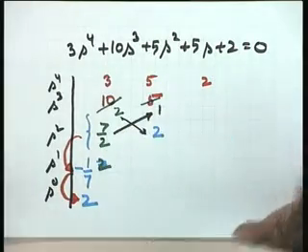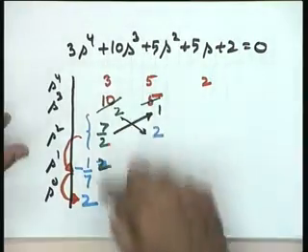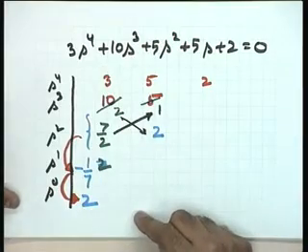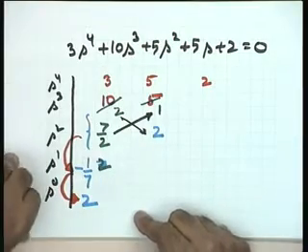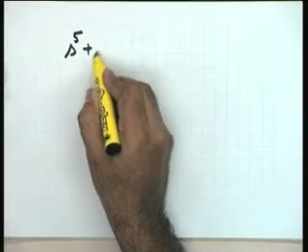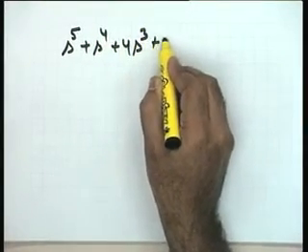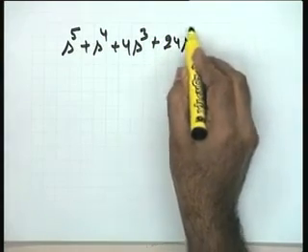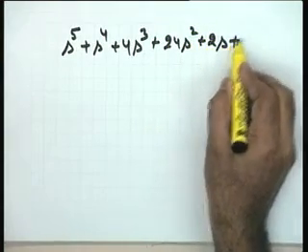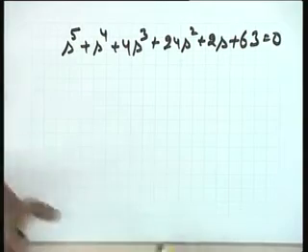There are definitely no roots on the imaginary axis if the Routh array formulation is like this. Now, let me go to a situation. Naturally, such a situation is bound to exist because the roots can be there on the j omega axis. And to come to that particular situation, I think I will take up an example first. s^5 + s^4 + 4s^3 + 24s^2 + 2s + 63 = 0.